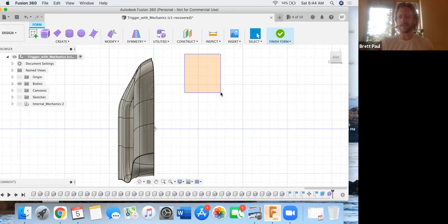I might have shared this earlier on in the lesson, but I'm sharing it again. If you drag down to the right and get that orange box, you're only going to highlight the segments that are fully inside of this box.